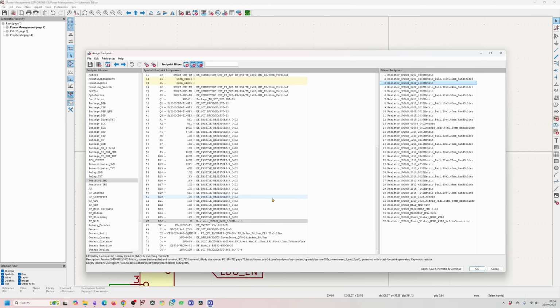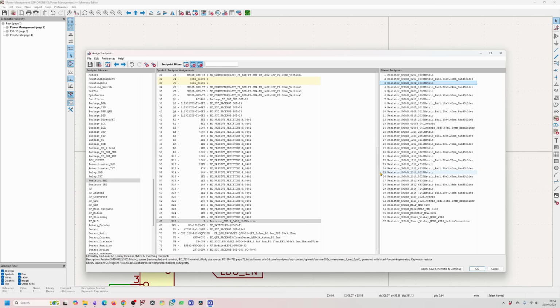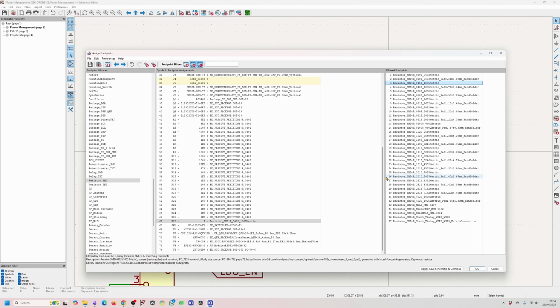Now you might have multiple components that don't have footprints, and you'd basically go into the default libraries for KiCAD, which has gotten a lot better recently, and there's symbols available for almost everything. There's footprints available for almost anything. But if the footprint is not available, or if the symbol is not available when you're creating your schematic, you'd have to create that yourself. So obviously assigning footprints is very important.